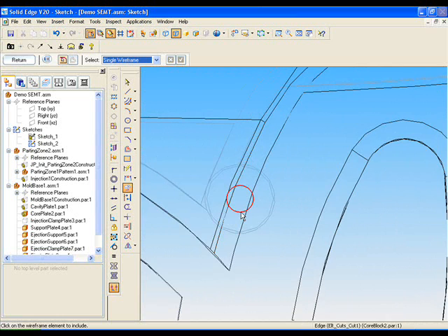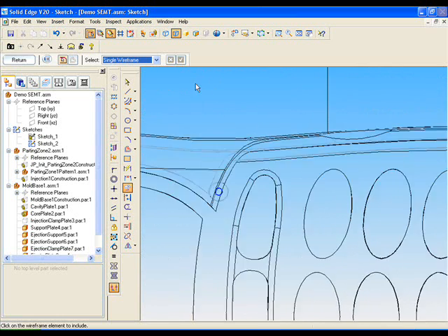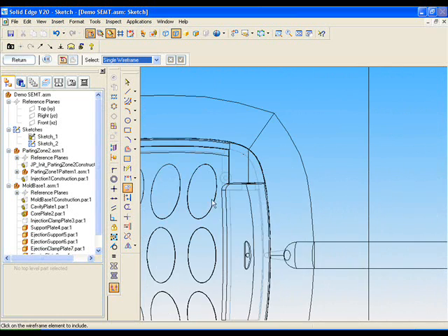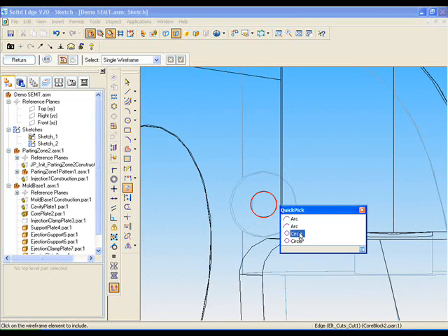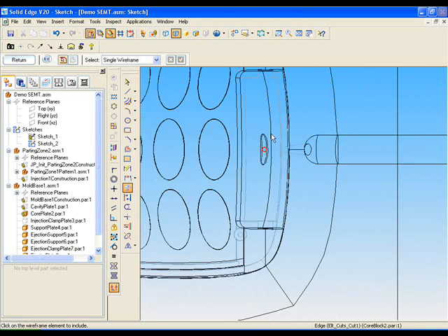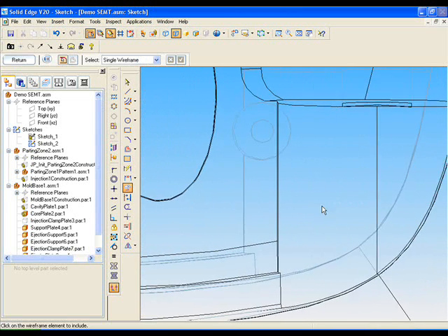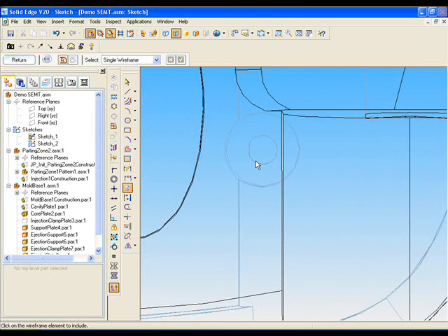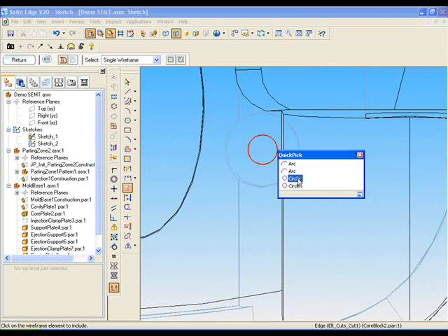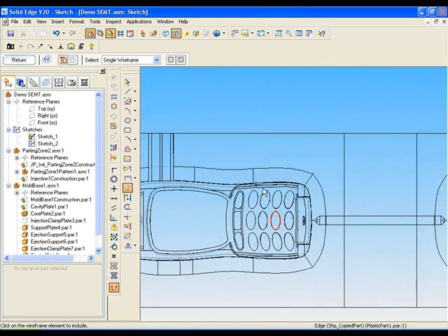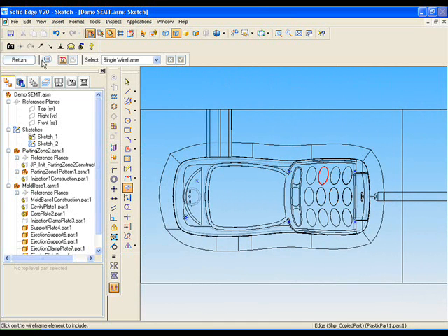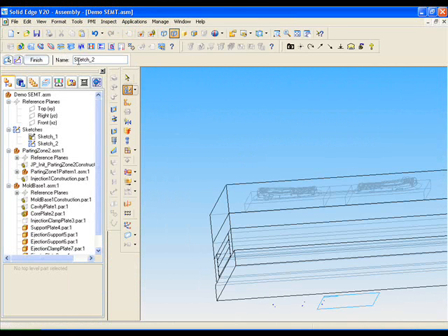The circles in the sketches define the X and Y position, but the Z level is not defined by the sketch's plane. The Z level is set by selecting a face, a plane, or, as is the case for ejector pins, is defined automatically to use the correct face of the ejector plate on the mold base. We'll now finish the sketch creation and rename it according to its purpose so it's easier to find when needed.